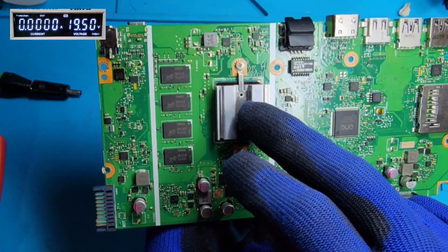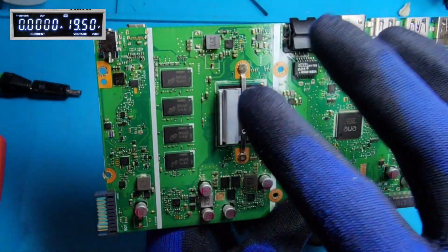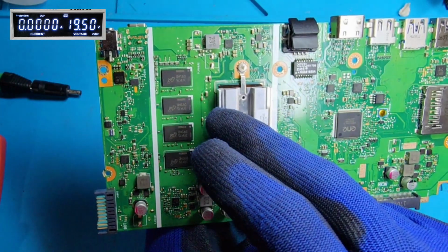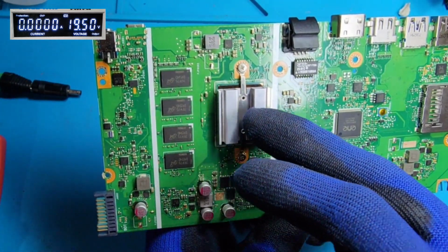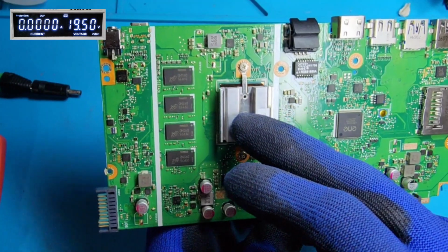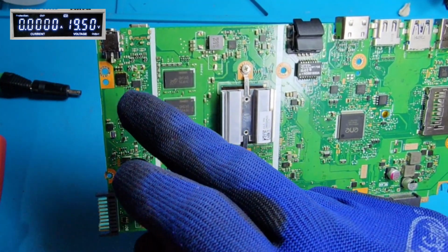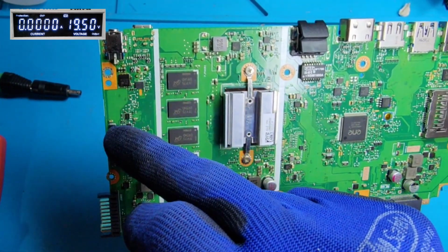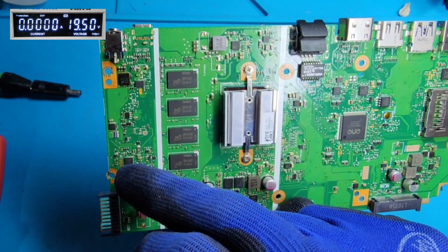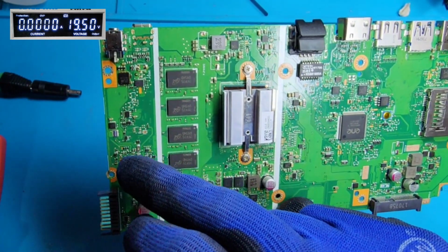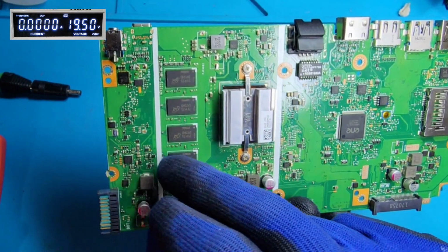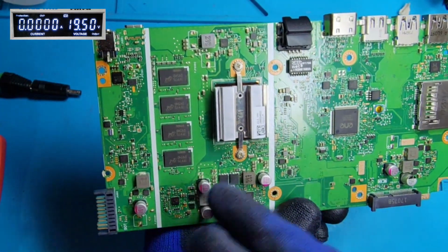In this kind of motherboard, this is just a small, low-end CPU here. But in high-end laptops, you will find an expensive CPU in that place. In that case, you must be very careful with the first and second MOSFET, and you need to provide the control of the first and second MOSFET to the charger IC. Then only it will detect the short and cut off the voltage into the main power rail here.